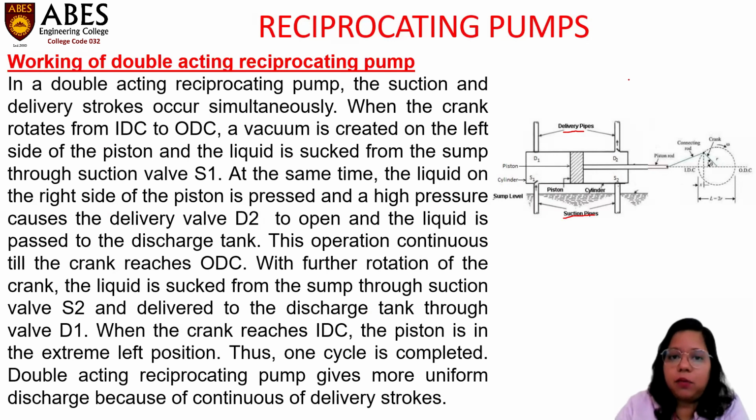In a double acting reciprocating pump, the suction and delivery strokes occur simultaneously. That was not happening simultaneously in the single acting reciprocating pump. In single acting, when the suction valve is open, the delivery valve is closed, and when the delivery valve was open, the suction valve was closed. But in the double acting reciprocating pump, it works simultaneously. Suction and delivery strokes occur simultaneously.